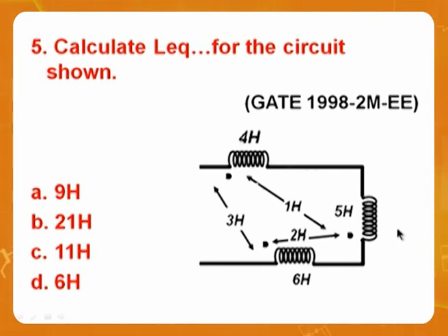This is coupling on this coil, this coupling on this coil, therefore 2. So minus 2 here. Then this is while leaving, this is while leaving, positive. That means 2 into 2, 4. Then this is while entering, this is while leaving, opposite. Like this, for both coils, you should understand whether it is opposite, meaning minus sign, or same, meaning positive sign, right?